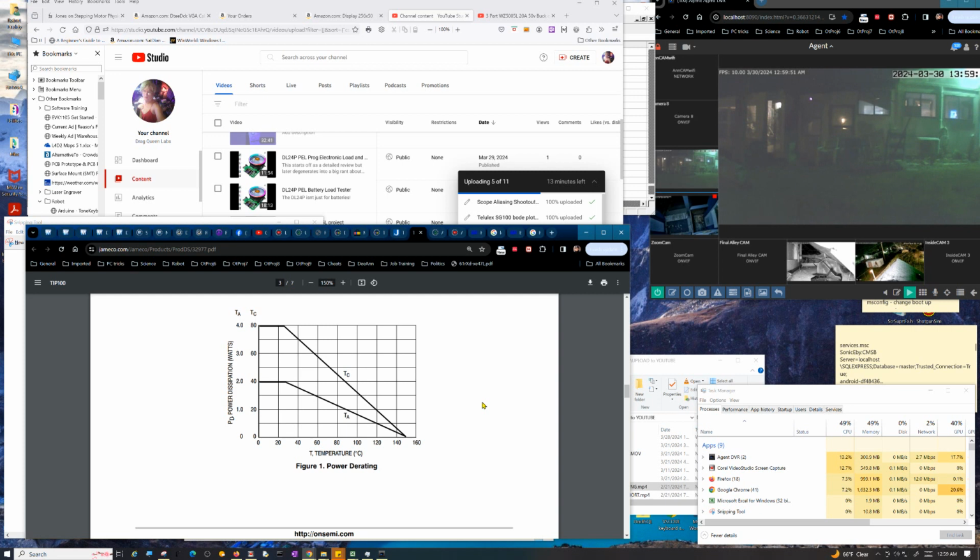It's just a matter of thinking about it logically. I still don't know what the standard specification would be. Sometimes manufacturers tell you what they define, but it still depends on how you're mounting your component. So you've got to think about where the cooling air is going to be coming from in your enclosure. It's not even a bad idea to do a little smoke test on it, with a cigarette or something generating some very wispy smoke, so you can see how the heat and the air are moving around that hot component.